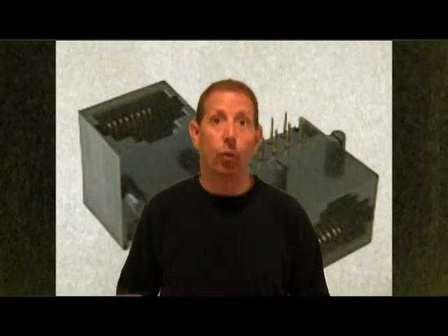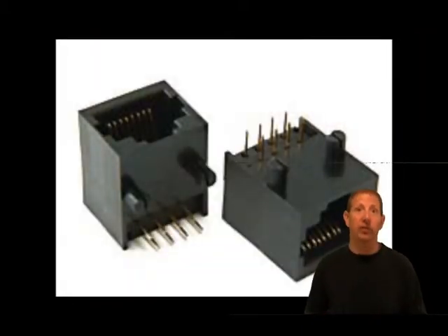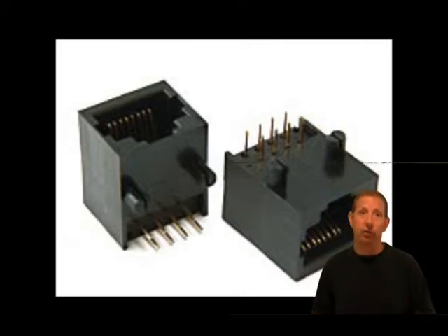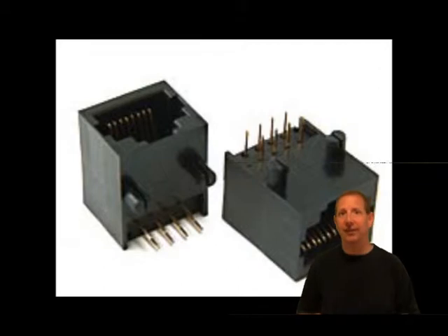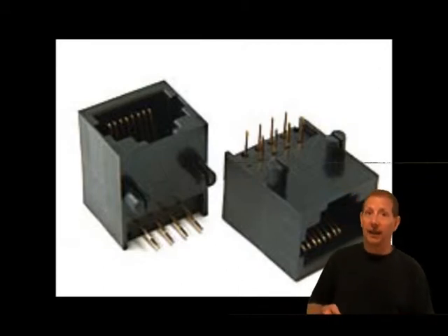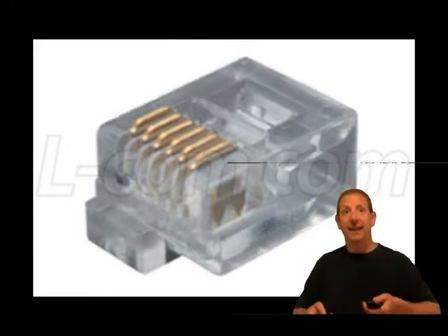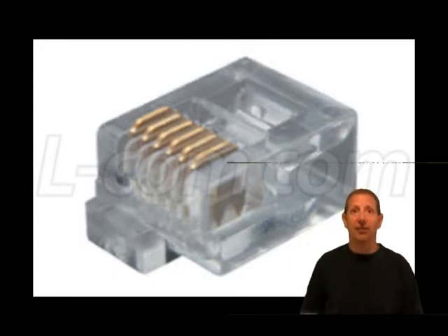The original intent was to protect delicate digital equipment from the higher voltages that can sometimes be present on telephone circuits. For example, the common open circuit voltage for a telephone line in the United States is 48 DC, and the ring voltage can approach up to 90 volts AC, both at low current. However, modern data circuits are fairly immune to these voltages, and the fact that the key jacks are easily defeated has led to their disuse.